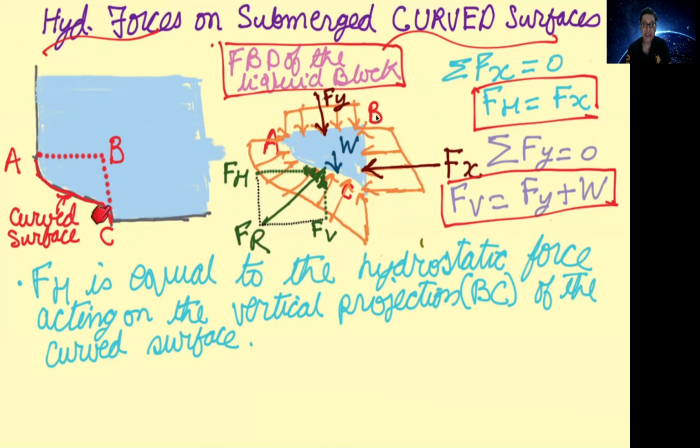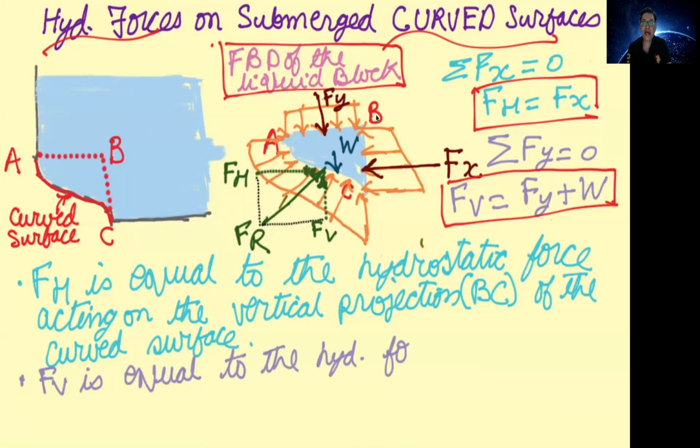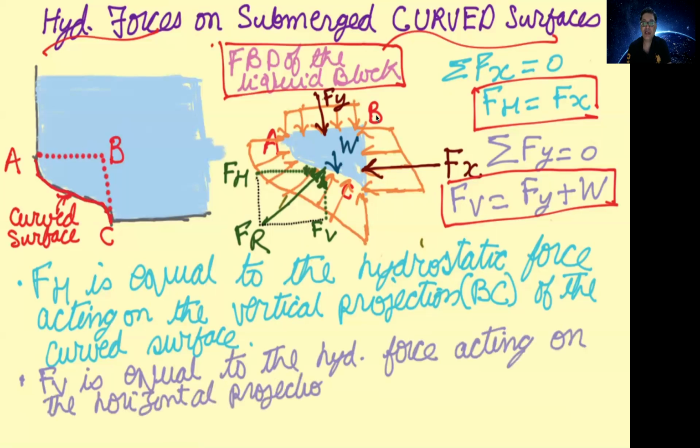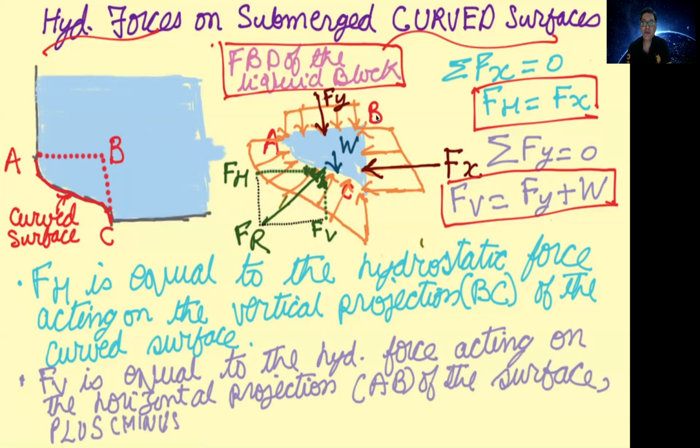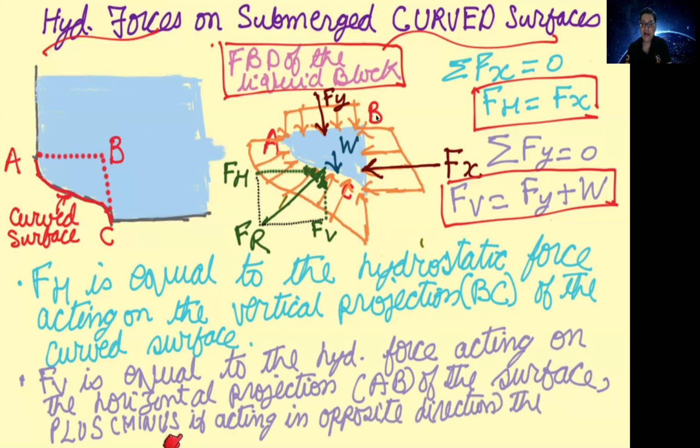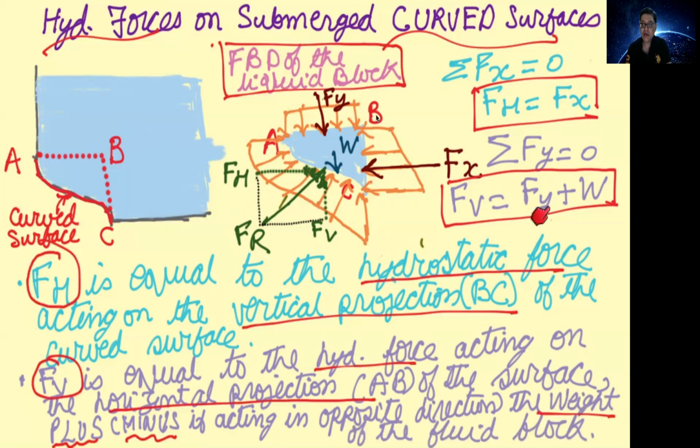Note that this BC is a vertical projection of the curved surface, whereas the vertical component of the hydrostatic force acting on the curved surface is equal to the hydrostatic force acting on the horizontal projection of the surface plus the weight.